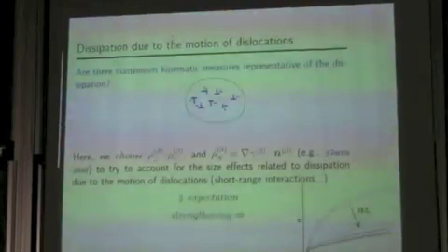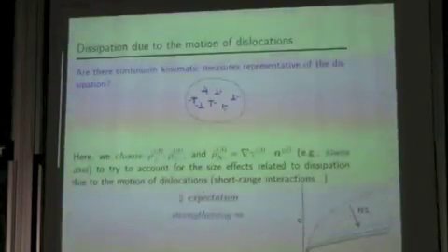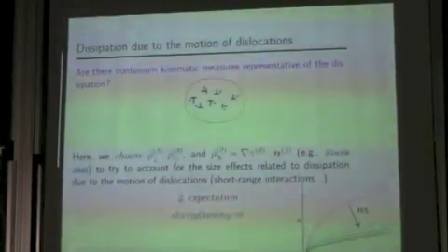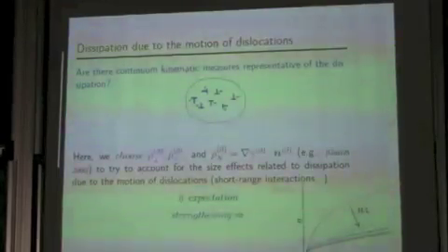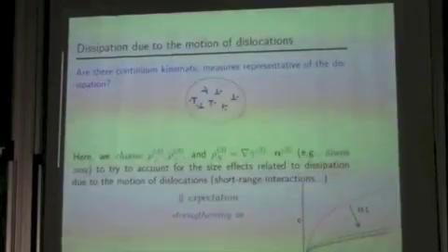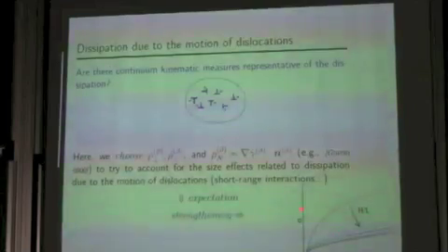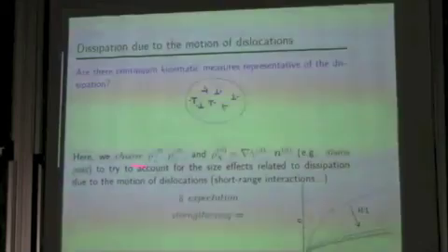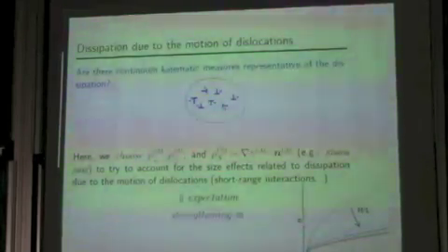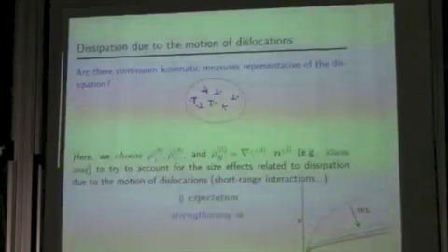But first of all, we were planning to implement a quite complicated hardening in the crystal plasticity model, so we didn't exactly know whether these terms could deliver a different size effect. Second of all, it turned out that they are useful for the computation. For the finite element computation, these terms help in reaching convergence.